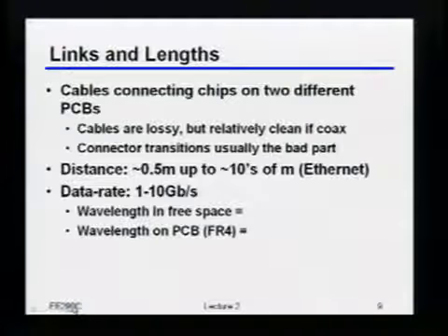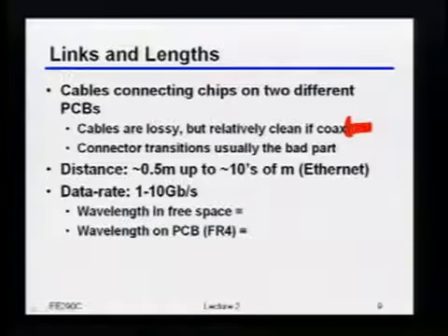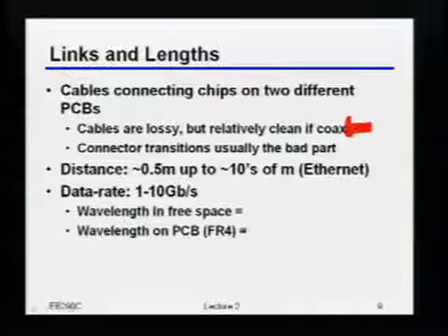It turns out that in those contexts, the cable itself, from a signal integrity standpoint, is typically pretty clean, as long as it's a reasonable coax cable. The only bad news is that it's a little bit lossy, or in fact, maybe even a lot lossy.